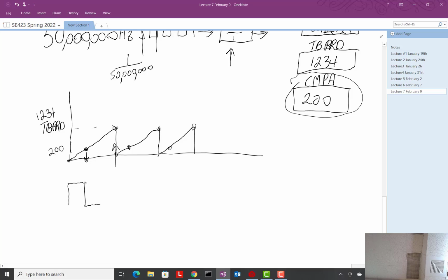And then it stays low until the counter equals 0 again. High. Gets to 200, goes low. High. Low. See what I'm doing? So, you did not have to pull that IO pin out. You're not going to do any GPIO regs clear or GPIO regs set and all that, remember? This is all done for you inside the CPU, inside the PWM peripheral.